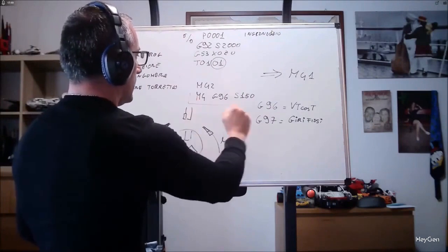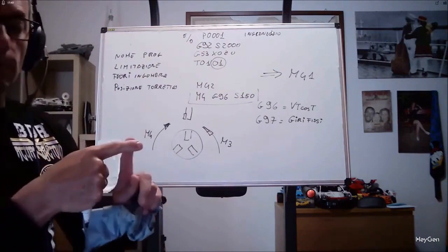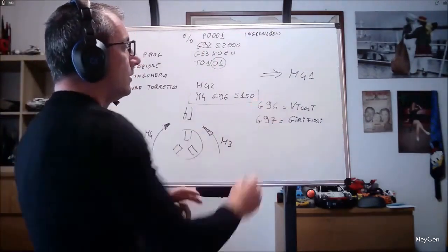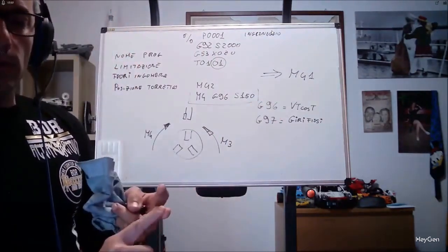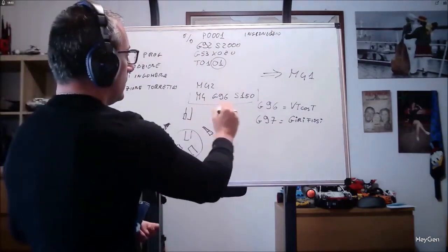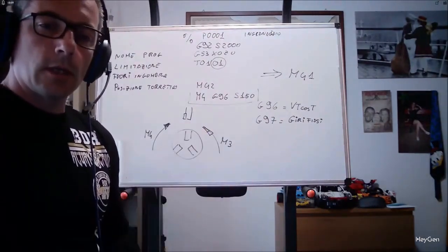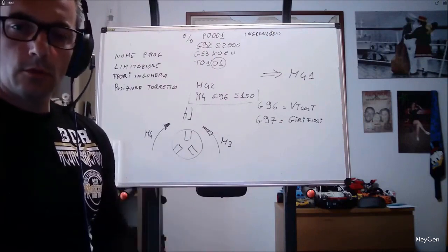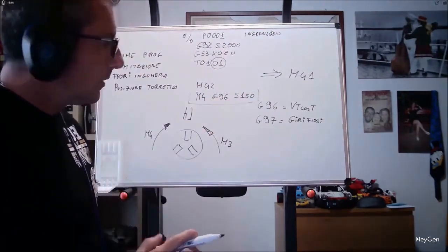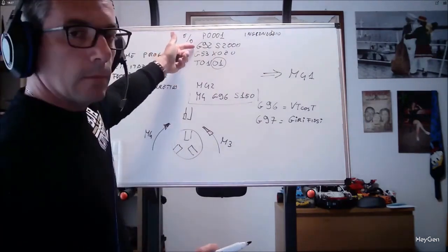So command line to make the spindle rotate. M4, rotation direction, G96 or G97, constant cutting speed or fixed RPM, and then to these two, how many fixed RPM to use, or what constant cutting speed to use. So G97 S150, any machining we program afterwards will be done at 150 RPM. No doubt about it. G96 S150, the RPM varies with the diameter until reaching a maximum of 2000 RPM.